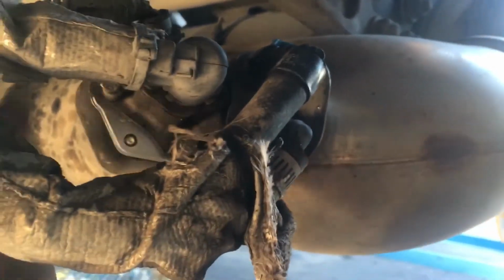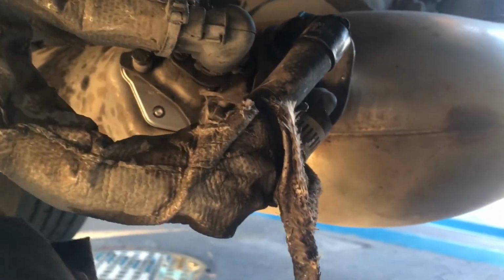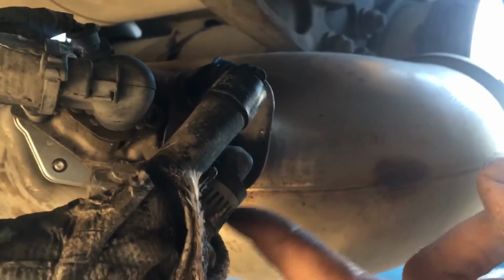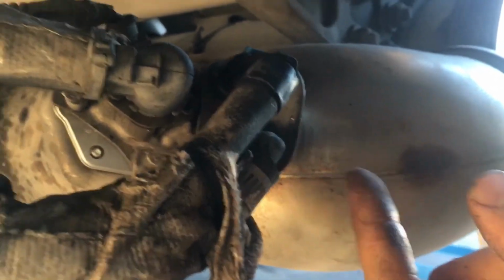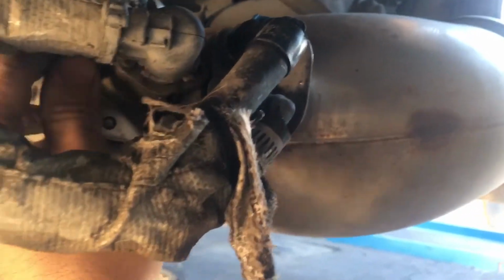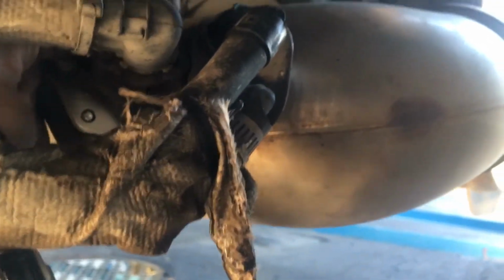Everything looks to be in place. You should check for crimping too, but usually that line is pretty protected from being crimped. And these two are your coolant lines. Runs coolant through this doser. And so our DEF system appears to be free of external leaks or damage.